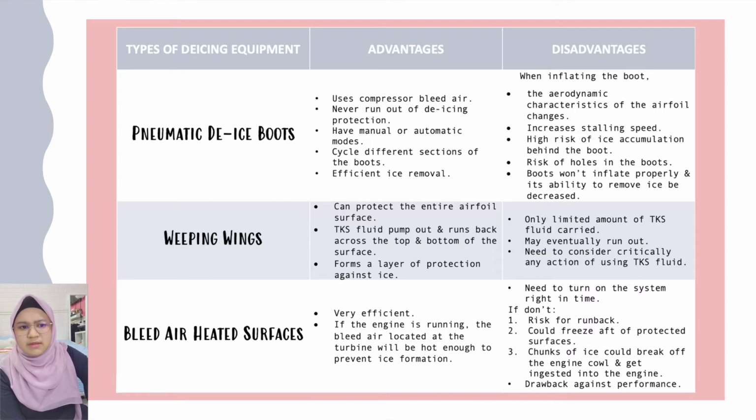The advantage of this is that it uses compressor bleed air, which never runs out of de-icing protection. It has manual and also automatic modes, which is very efficient for ice removal. But the disadvantages of this are that when inflating the boots, the aerodynamic characteristics of the airflow surfaces change. It can also increase the stalling speed, and there is a high risk of ice accumulation behind the boot and risk of holes in the boot.